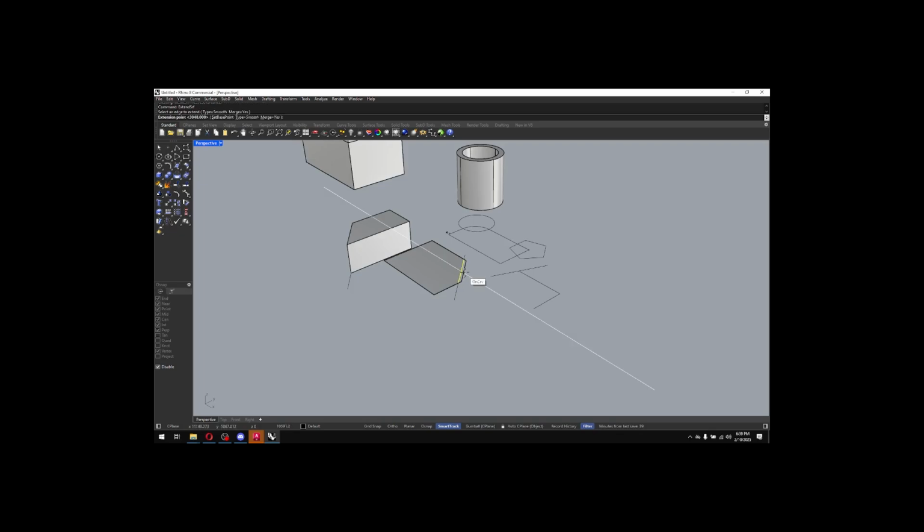If I did that on this corner, it's going to extend that surface the way that it thinks it's naturally wanting to go. So it's not extruding that line, how it looked like on this one. This one just looked like we were extruding to the side. This one, it's going to take into account this line and that line. So if I click there, you can see it's wanting to almost rebuild the part that we trimmed off. That will work on any shape. As you're doing different versions of this, as you're extending things, you'll start to realize they come to a point or they'll start to wrap in a real weird way. So you just have to keep an eye on that when you're extending surfaces.